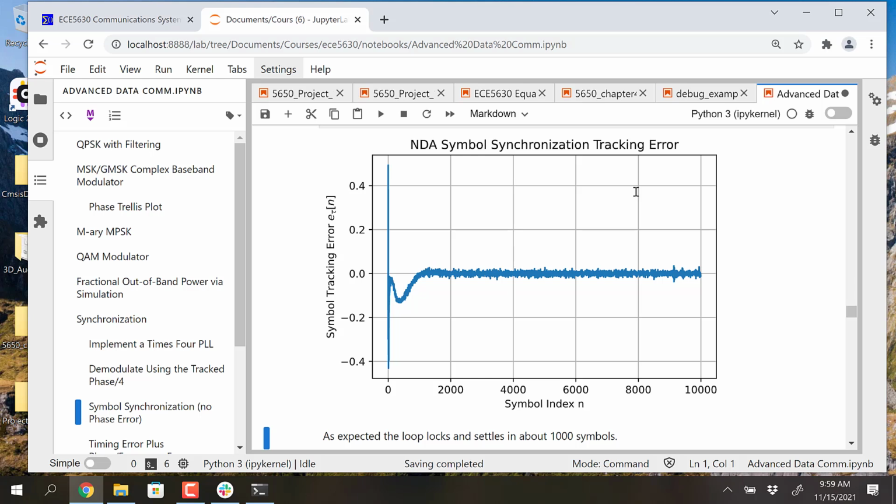I mean, there's data related jitter in a tracking loop too. It's not just due to noise, there's due to the data patterns, and that's why people will talk about tracking algorithms and what's the density of the transitions. Most tracking algorithms, if you take away, well, just take a baseband waveform like NRZ waveform. If it was all ones, it would just be high or -1. Can you get a clock out of that? No, you don't have any transitions, you can't get it.